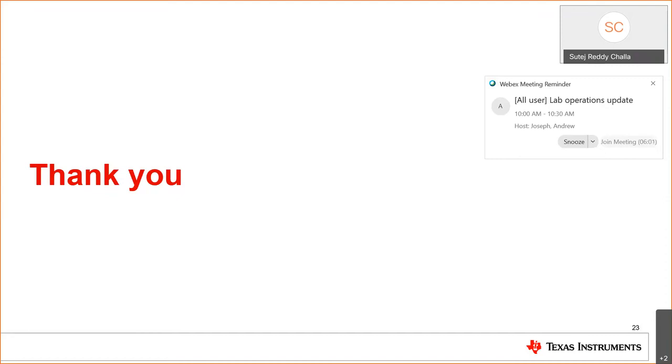Okay, thank you, Stage. There's another question that's so relevant. How about the consideration of turning off the switch? I heard that the SiC FETs are sensitive to negative VGS. So Stage, maybe I give you some hint: try to mention how the negative VGS affects the SiC flyback. How does it affect the turn-off loss, and what additional implication from the device performance perspective?